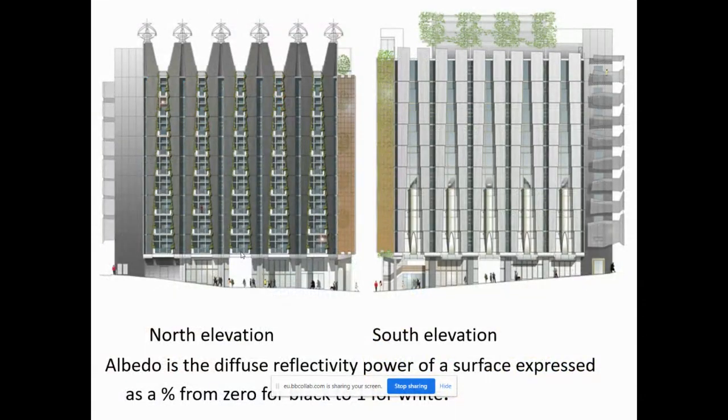So there you have the two: the north facade, the south facade. The south facade is silver reflective because that's where the air is treated on the roof and pumped down and fed under the floors on the south side. The pipes in between on the windows are made of ETFE, so they're transparent, and they are cooling towers.